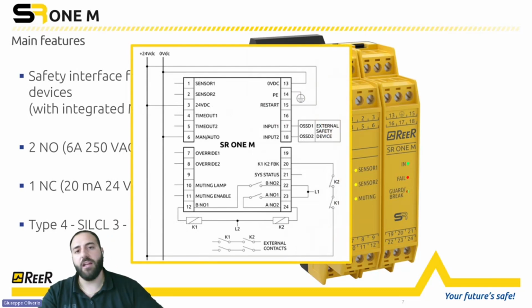We have dedicated inputs with dedicated functions. So we have sensor 1 and 2, where you are going to connect your muting sensors, the timeout selection. Based on the wiring of timeout 1 and timeout 2, you will decide the muting timeout.